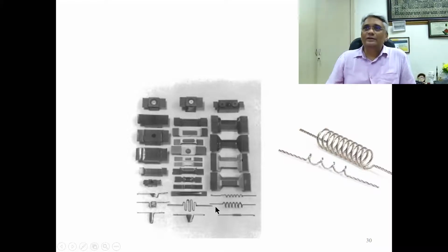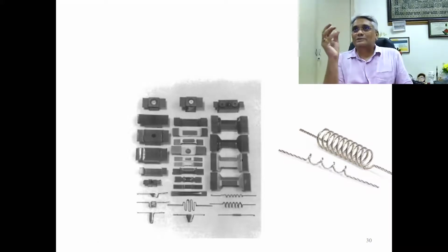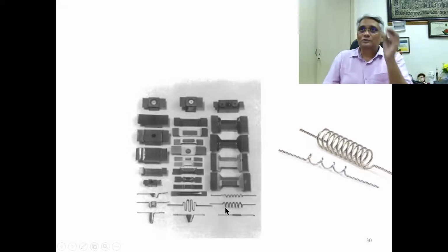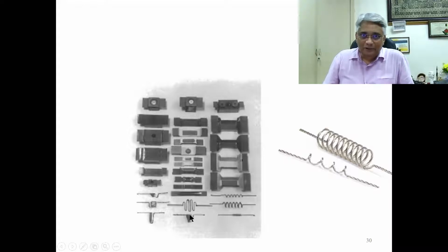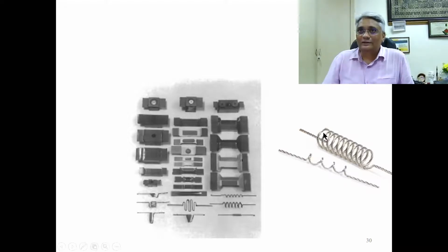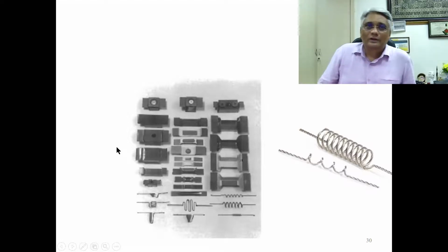And the whole idea is, you know that as the melting process is on, the charge which is in a solid form starts losing its volume. And as it becomes smaller and smaller, right, it is pushed through the conical basket arrangement, where it is still held at each of those rings. Unlike in this case where it can go down much faster, right? This is a very logical way of designing these wires in a conical form. So it all depends on one's requirement,